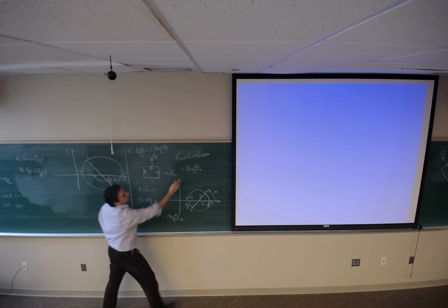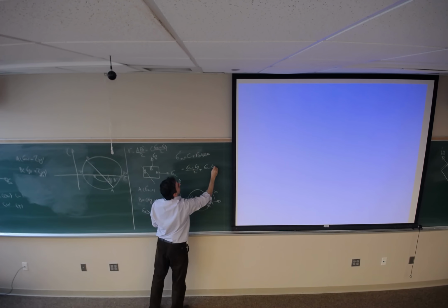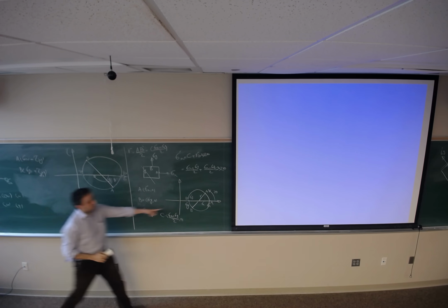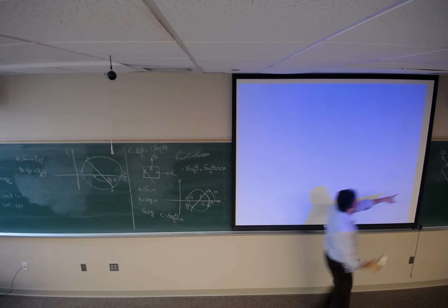So the value of sigma prime x at the plane which has point A located on it is going to be sigma x plus sigma y divided by 2 plus sigma x minus sigma y divided by 2 cosine of 2 theta.